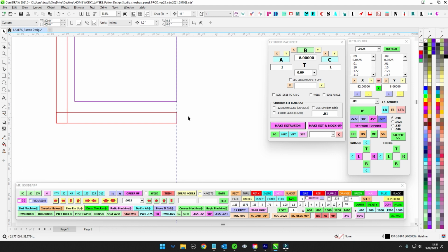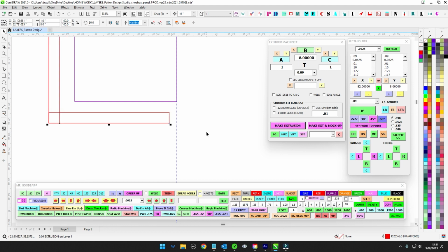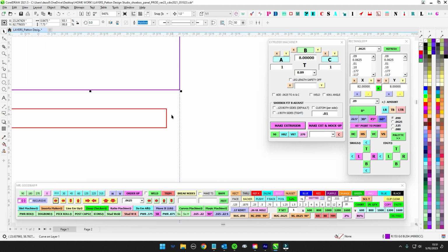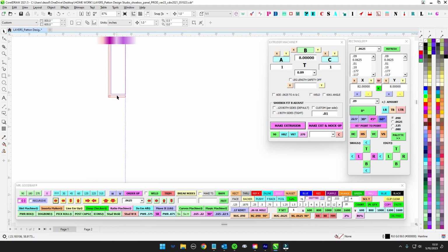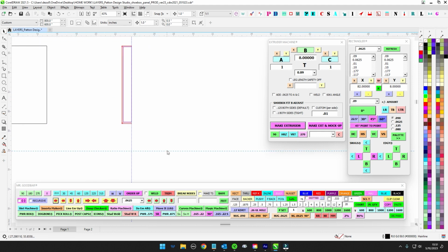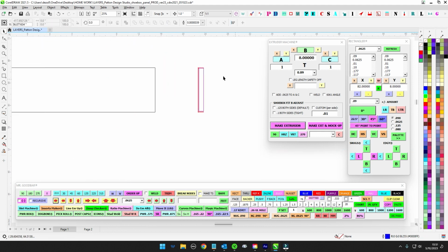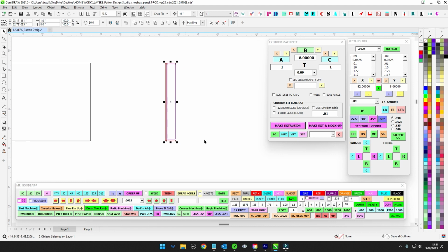Now, sometimes you don't want the face to go all the way against the wall. Maybe you want it to float a tiny bit off. There's a 1/16. Then what you'll do is make the backer be the one that it bottoms against, and set that depth by using the backer as the depth setter, right? So it's all about, again, you got to know what's going on. You got to think it through. But this side profile helps you figure that out.